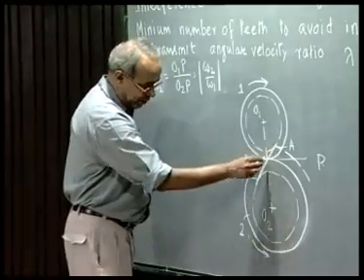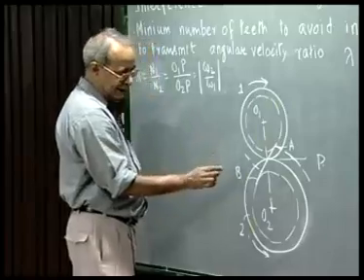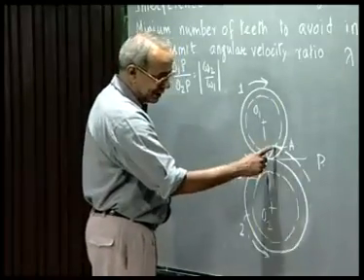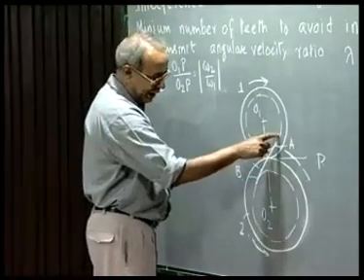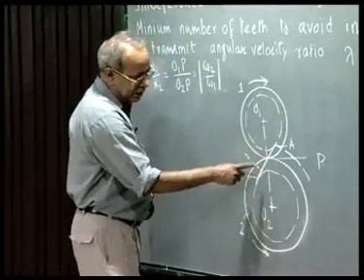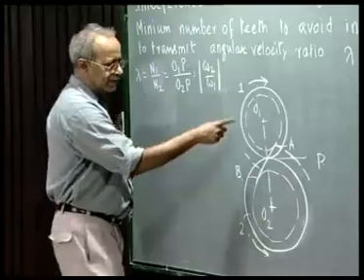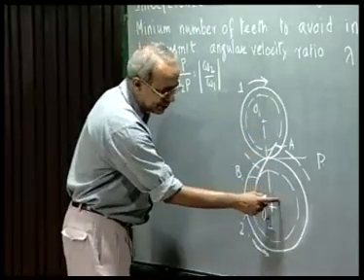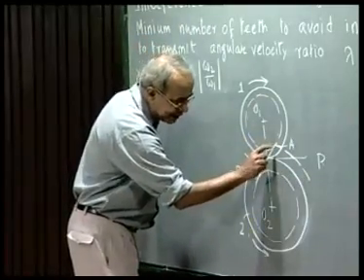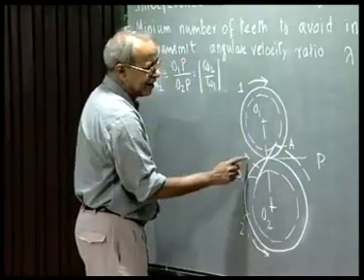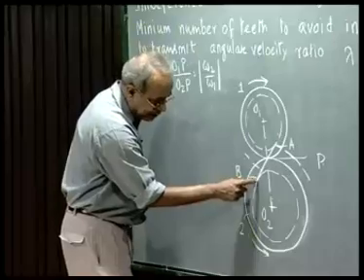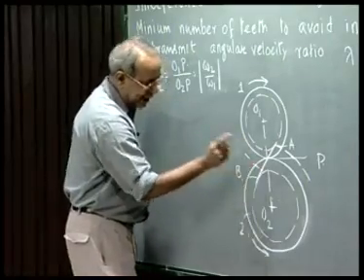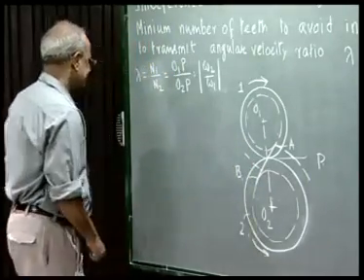The point of contact always lies on this line, so I am only interested in seeing whether the addendum circle intersects AB beyond A or beyond B. So interference obviously occurs first with the pinion when the addendum circle of the gear just passes through the point A, because even at that time the addendum circle of the pinion does not pass through B, it is still to interfere with this gear.